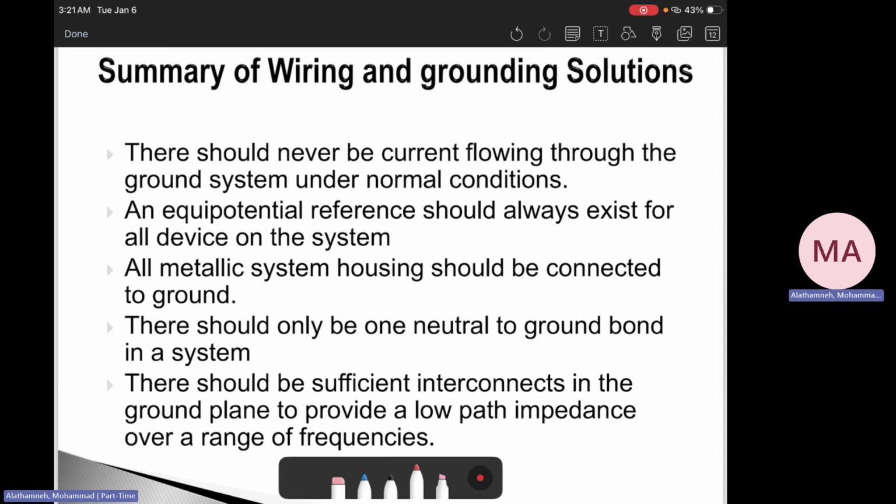Okay, so when we think about grounding, it is like the language all devices agree on. This is the right zero. This is the zero that we need, or the zero that we will consider. If your building has 5 different zeros, where your zero is different than the zero of the other room, the zero of your neighbor, and so on, that will create a floating zero. That's something we don't want. So your devices will argue about which ground is the correct ground. Then the argument appears as noise, resets, trips, and sometimes shocks. So your job as a power quality engineer is to make sure the building speaks one grounding language, only one ground. Multiple grounds create a problem.